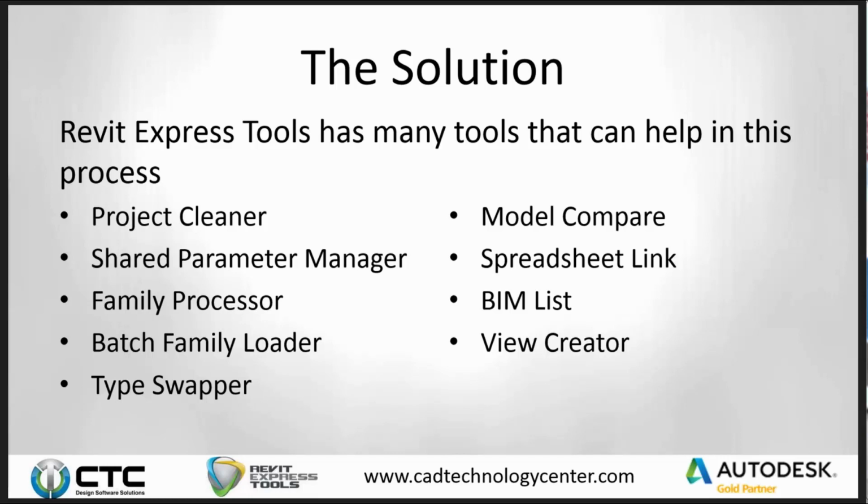There's the Family Processor to go through actual family content and bring that in alignment with the actual shared parameters that have been modified. There's Batch Family Loader, which is a fantastic tool for taking a bunch of content that's been updated and loaded into a number of projects. There's Type Swapper, which can help with resolving inside the project some issues with different types, and we'll take a look at that tool eventually.